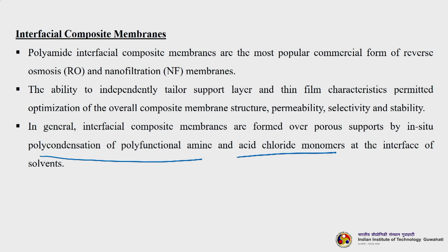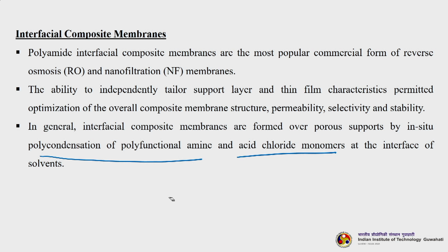Now, students, we have understood how the interfacial polymerization actually works, so I am not going to repeat this. I am just quickly telling you. You have a membrane, let us say this is a membrane having some holes. You impregnate this with your amine, so that goes into the pores and on the surface. Then you keep it in contact with the acid chloride. So, this is your amine